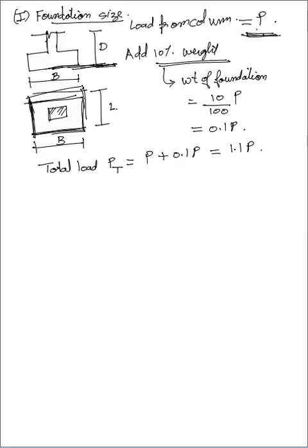So the total load PT will be 1.1 P. Remember here P is unfactored. Let me write, for LSM we are using unfactored load for calculation of area.